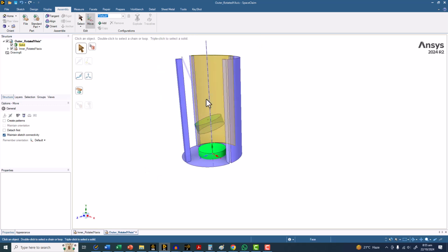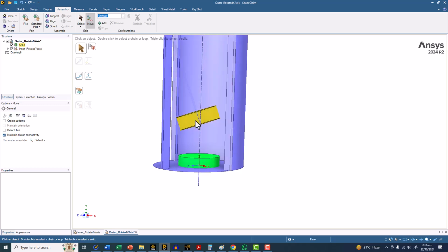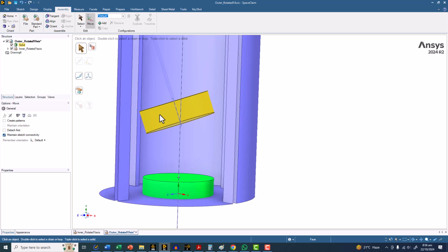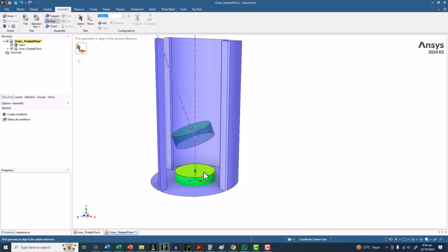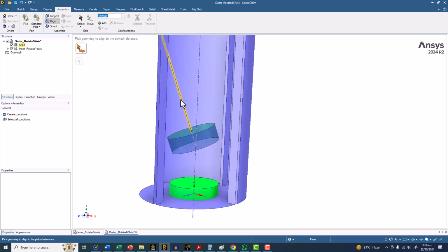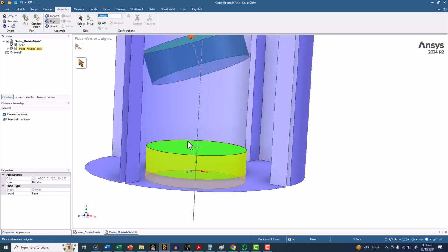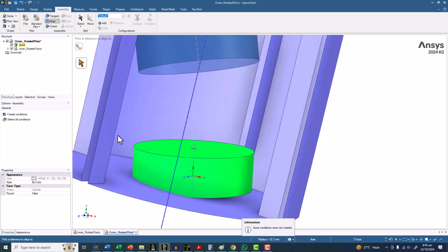Now the tank is straight and our geometry is straight, but the issue is that this is not the proper point. The impeller was inclined at some angle, so we need to match them. Okay, so we have the align condition. So I'm going to first align my tank with my impeller geometry. What I'm going to do is use the axis of the tank, the outer domain which is stationary, and I will align that one with my inner domain axis. Okay, like this.